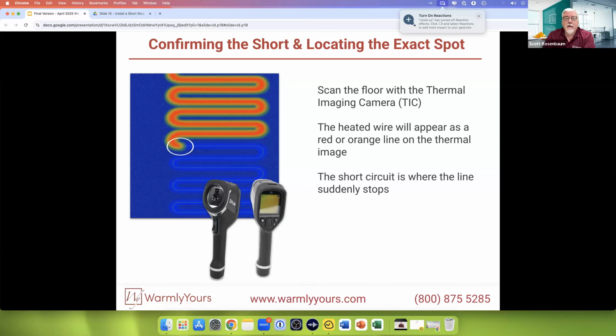So at this point, let's say, Anatoly, let's go back to that previous one: you turn the dial, you're getting 1.5 to 2 amps, and then all of a sudden the amp draw goes to 0. What happened? Yeah, if your amps drop down, that means, first of all, there's no power being drawn. And the reason there's no power being drawn is very likely there's no short anymore. Again, maybe it was too much voltage. Maybe that short was so fragile that it just disconnected. That's where you will need to dive into a slightly different process with a high pot that we'll cover in a moment.